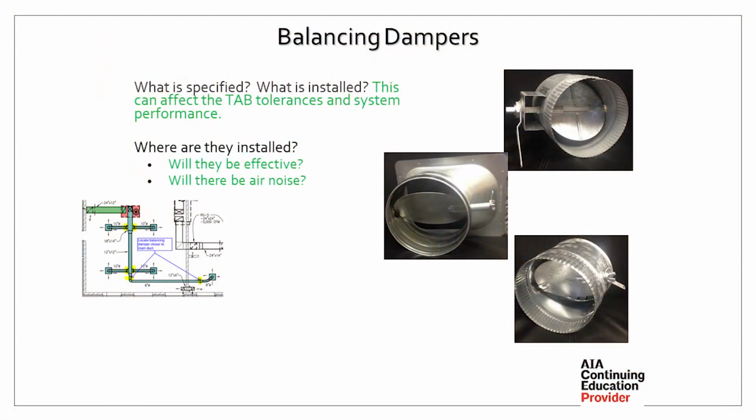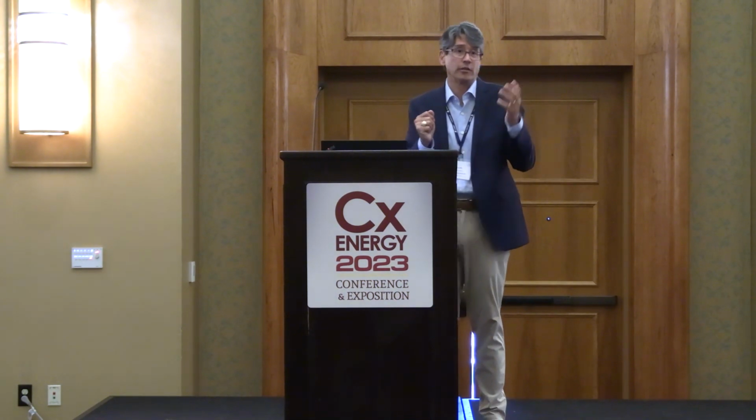Like we talked about, equipment can affect the balancing that gets done. Simple little thing: balancing dampers. Lower right is typically what we see the most. Handles are always buried in externally wrapped insulation. Can't find them. Set screws don't stay set. Believe it or not, you can close that damper on a 200 CFM outlet. My guess would be less than an inch of static pressure on it, and it's still going to leak through probably 50 to 75 CFM.